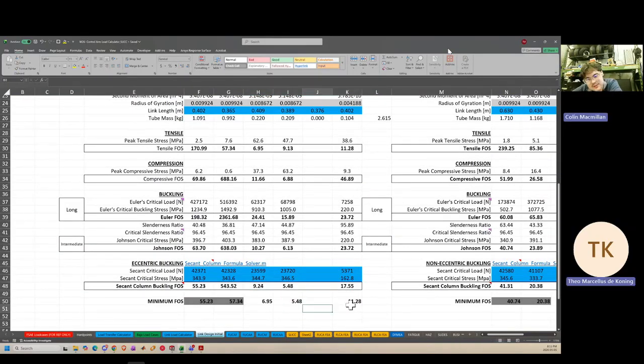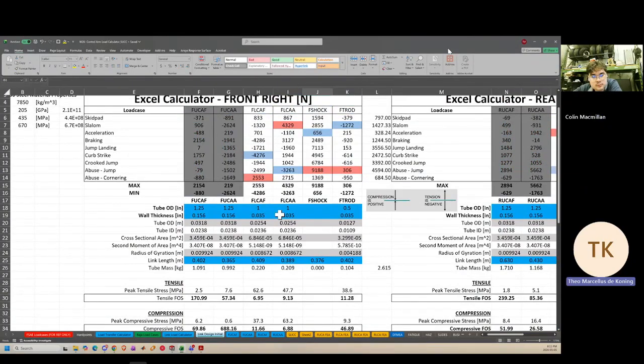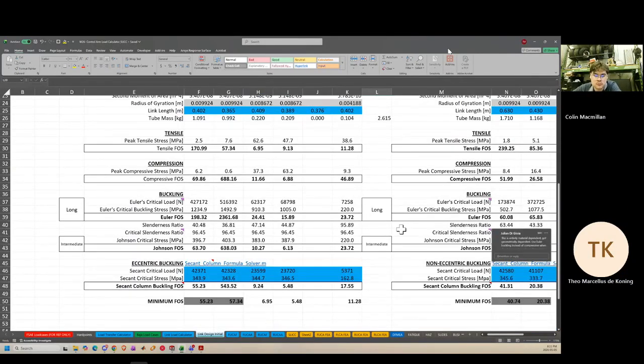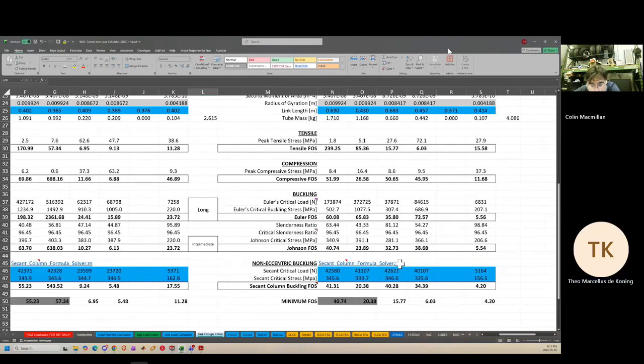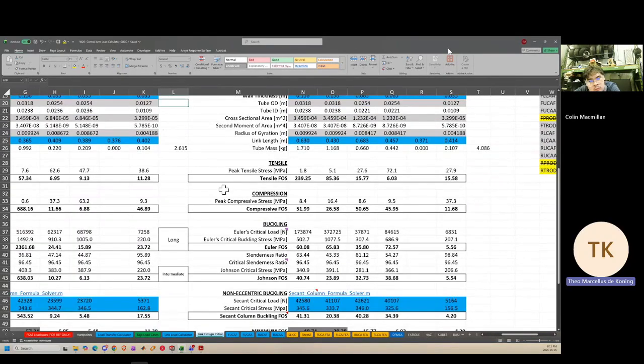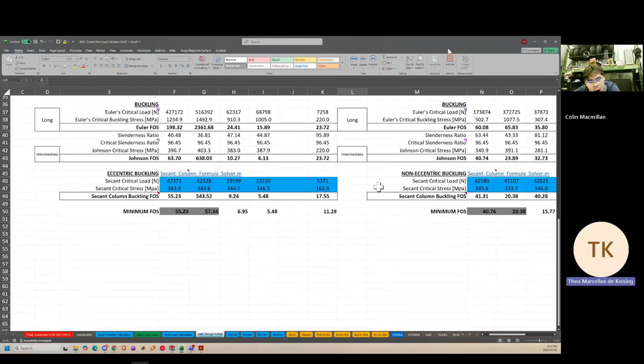So we still like 5 is high. This is just to make sure that we don't do all the work of designing a control arm and then putting it in ANSYS with something that's going to break immediately. Okay. Yeah. So these are already super thin tubes. Like these are 35 thou. Right. And this is just the same thing for the rear. Basically, play around with these numbers until you see something that's all right.